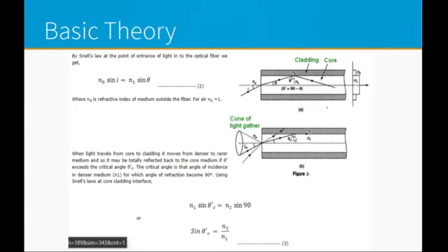At that point the refracted light basically grazes the core part and remains inside the core itself. So it is not going to get into the cladding part and is not lost. This is actually the boundary condition where angles beyond this angle would retain the light inside the core part. Otherwise it would be lost in the cladding.